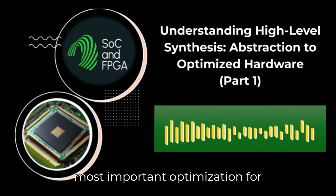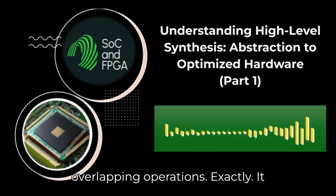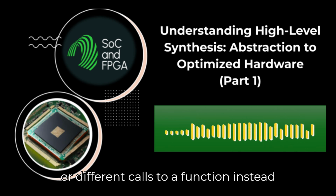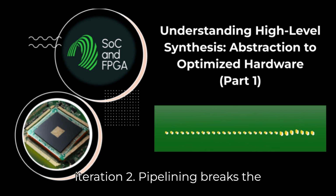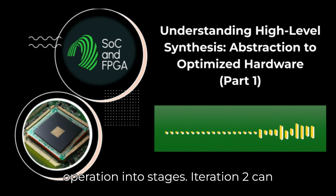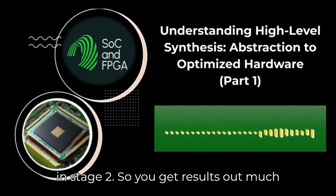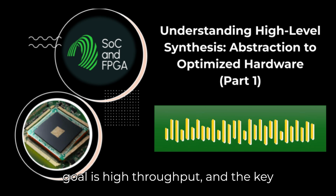Pipelining is maybe the most important optimization for throughput. Think of it like an assembly line for your loop or function. Overlapping operations. Exactly. It overlaps the execution of loop iterations, or different calls to a function. Instead of waiting for iteration 1 to completely finish before starting iteration 2, pipelining breaks the operation into stages. Iteration 2 can start stage 1 while iteration 1 is in stage 2. So you get results out much faster, more frequently. Precisely. The goal is high throughput.